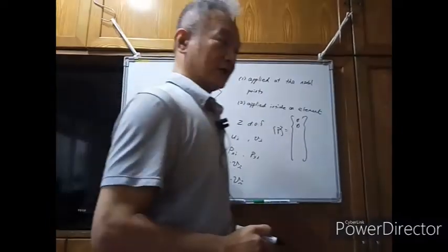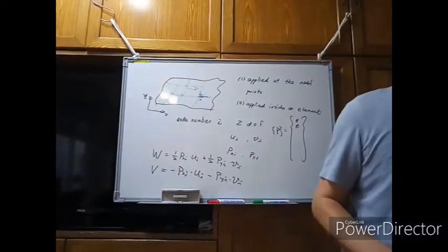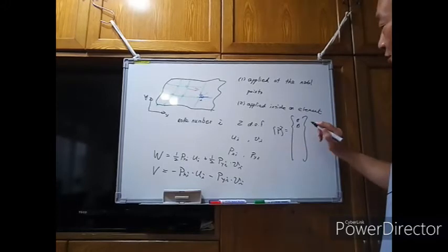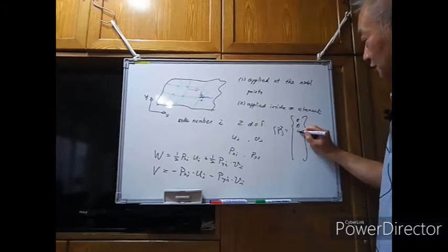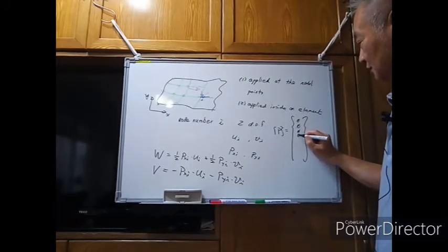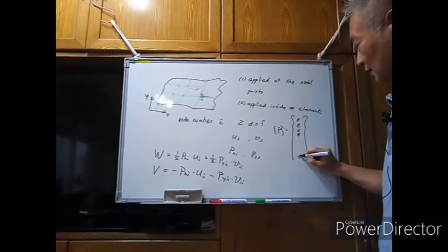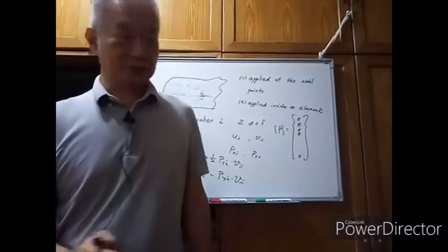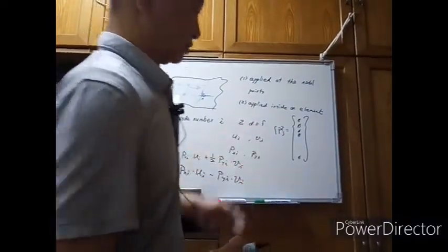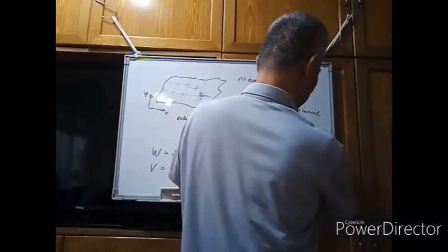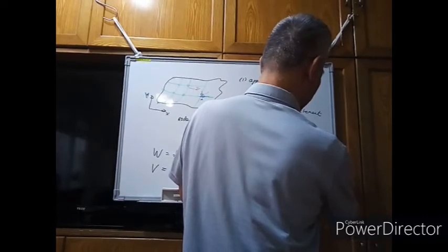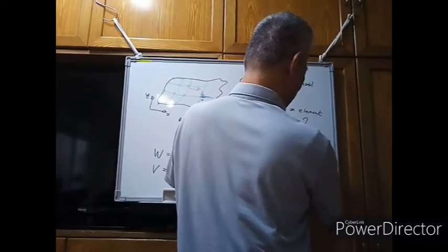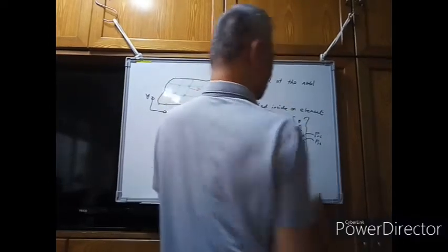The initial values of the load vector are usually all equal to zero. So first we need to assign the elements in this load vector all equal to 0. And if the user tells you we have the pxi and the pyi, you just assemble them into the corresponding position.